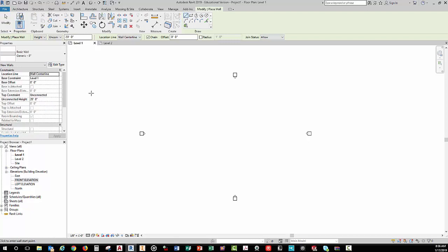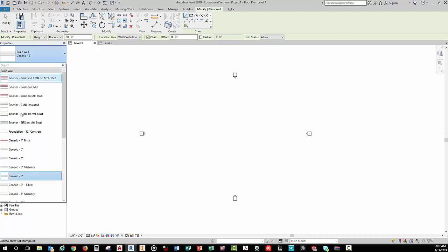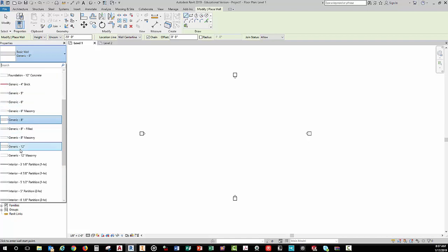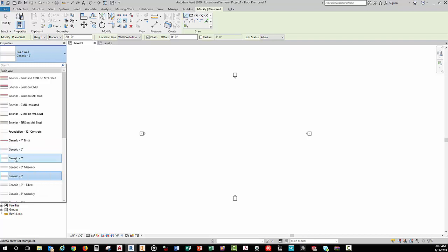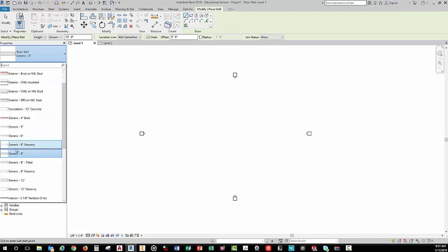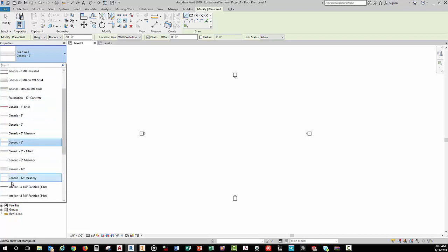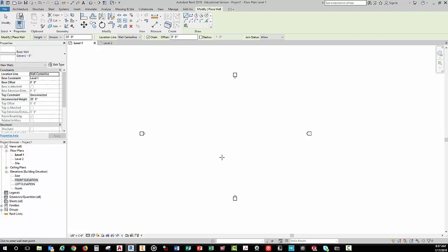All right, so let's get down to, in the book, it shows you how to draw walls. So, right, you start off with walls. You click on here, and so it says to pick, you know, an interior, exterior, something, right? I think it says to pick a generic, and see, you may end up with different walls because I picked architecture. It may have said pick construction. I don't remember. Or here's a generic 8-inch wall, right? Or generic 6-inch wall.